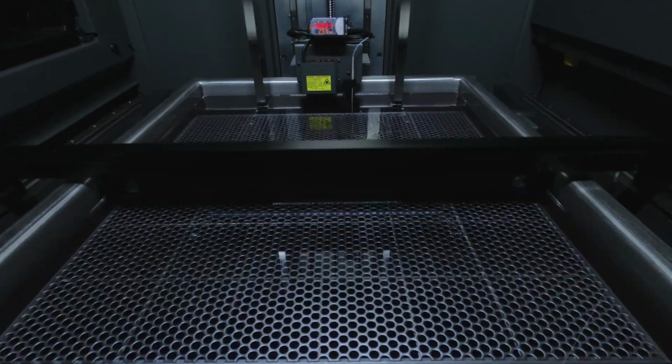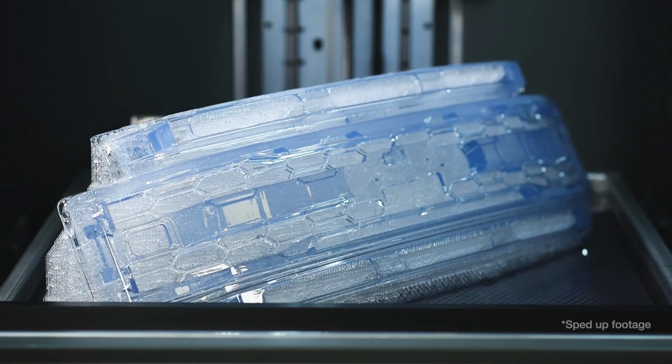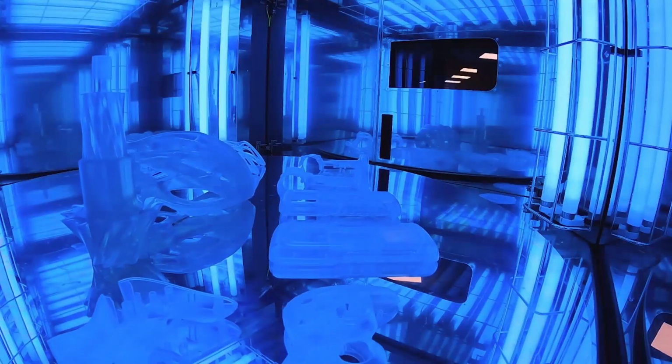And the difference between these home or more affordable printers is that there is a pool of resin. Essentially, your whole print is submerged in the resin. So the laser comes from the top. It draws essentially your layer, and then the layer drops down and is submerged deeper and deeper. And then after the print is finished, it has to go up and come out of the liquid.